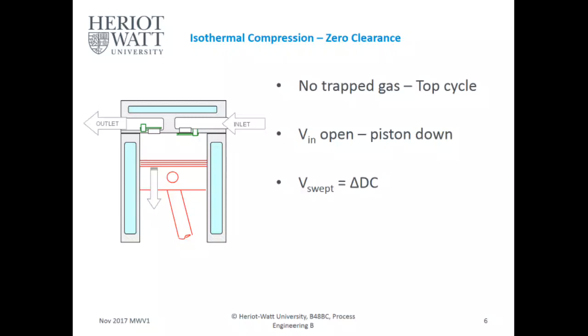So the swept volume is the volume swept out of the piston from the top dead center. The top area is always called the top dead center. In this case, it's 0. Imagine your syringe is all the way at the top, and you move it down. That's your top dead center. And when you get all the way to the bottom, that's your bottom dead center. So from the top dead center all the way to bottom dead center. The top dead center, as I explained, is basically the top of your piston, and the bottom is the farthest point your piston moves within that cylinder.